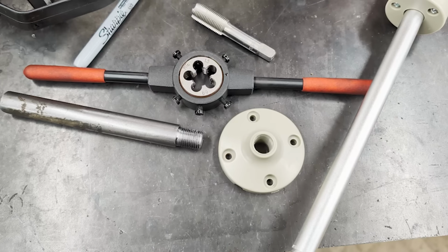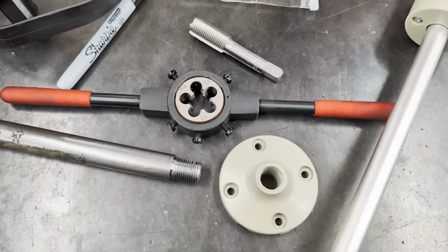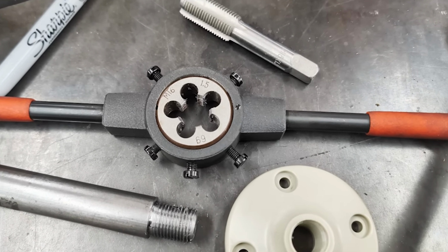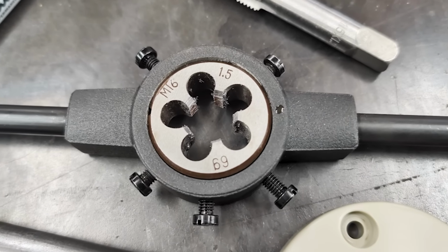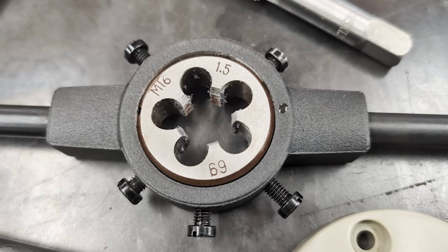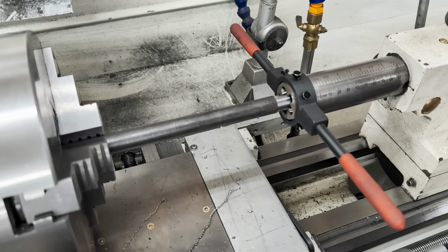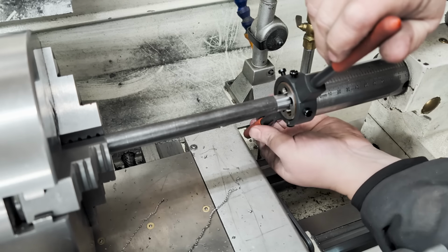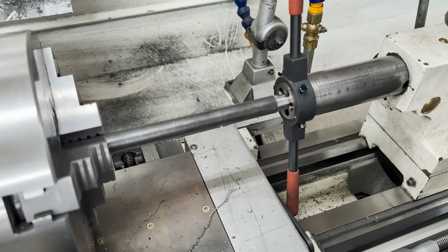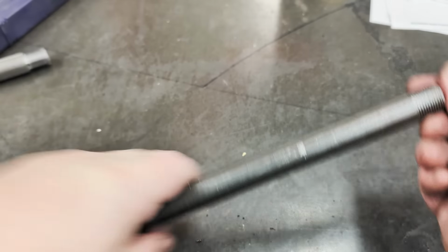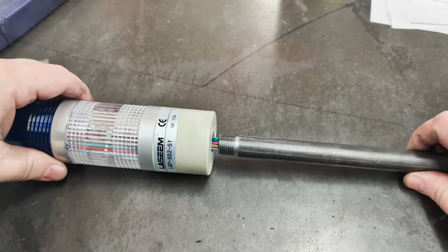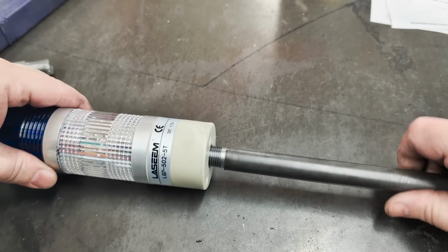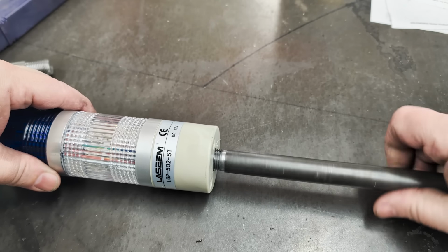Getting the stack light to actually mount on the mast was a bit annoying, as there was no indication what the thread on its base was. I eventually figured out it was M16 by 1.5, and picked up a die for that. 3/8" pipe is pretty close, and a lot more available around here, so I turned down the end of some of that to 16mm and threaded it. I have got to be a bit careful when screwing on the stack light not to cross-thread it, as the sharp steel threads I cut would chew up the soft plastic ones without even trying, but otherwise it works well.